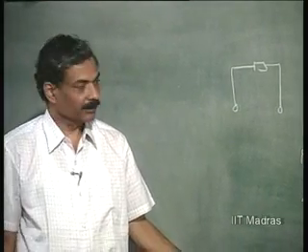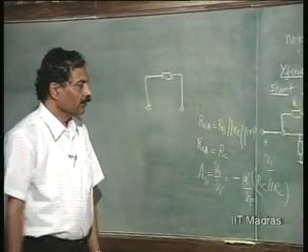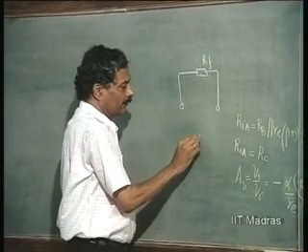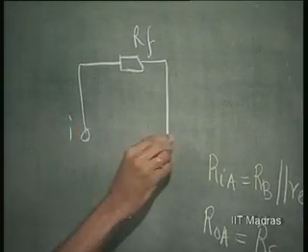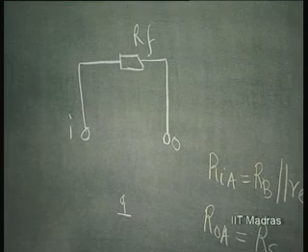That is the easiest, because it says Y feedback. So, Y parameter is the easiest. For this RF, what will be the Y parameter? This is the ground, this is the input, this is the output. So, what will be the Y parameter? Y parameter is known as a short circuit parameter, right. Both input and output will be shorted and the Y parameter will be measured.